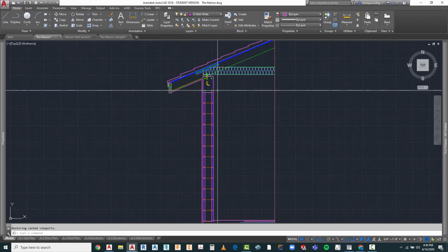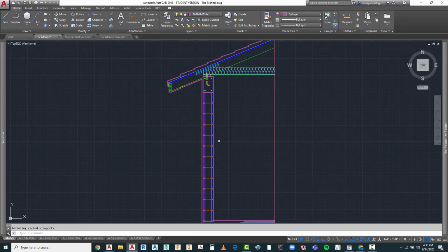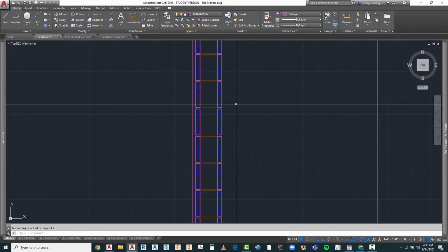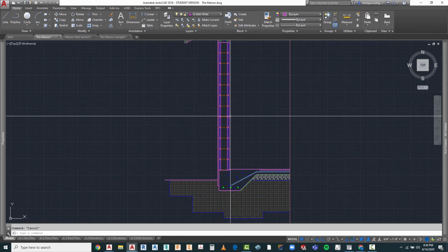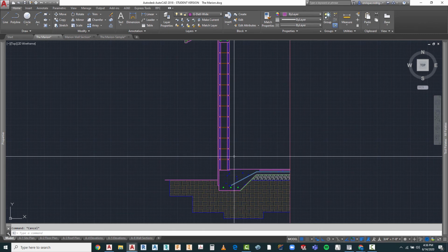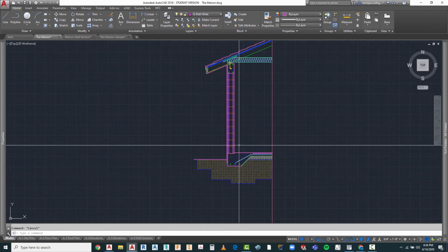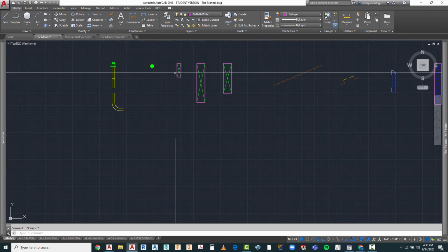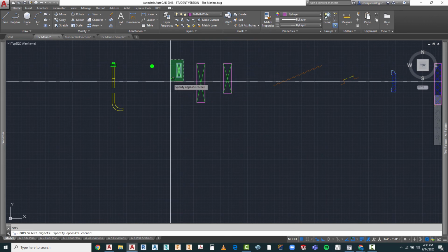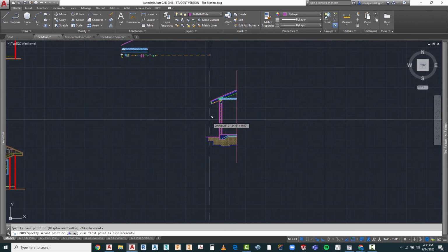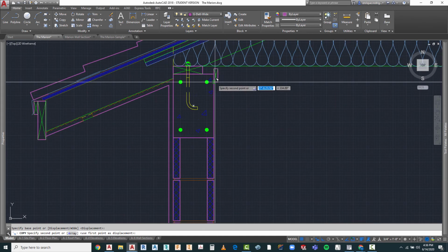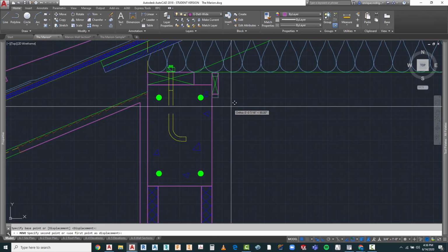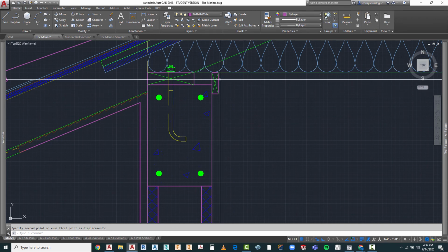Now the first thing that we're going to do is use a 1/2 inch drywall up against the concrete masonry units here. But it can't go right up against it. So we're going to create what we call furring strips. Furring strips are vertical items of wood, 1x3s or 1x2s, which would be these elements here. For the height of the wall, we're going to locate 3 of them. We're going to locate one at the top. I'm going to move this up a little bit. And this is going to provide nailers for the drywall going this way.